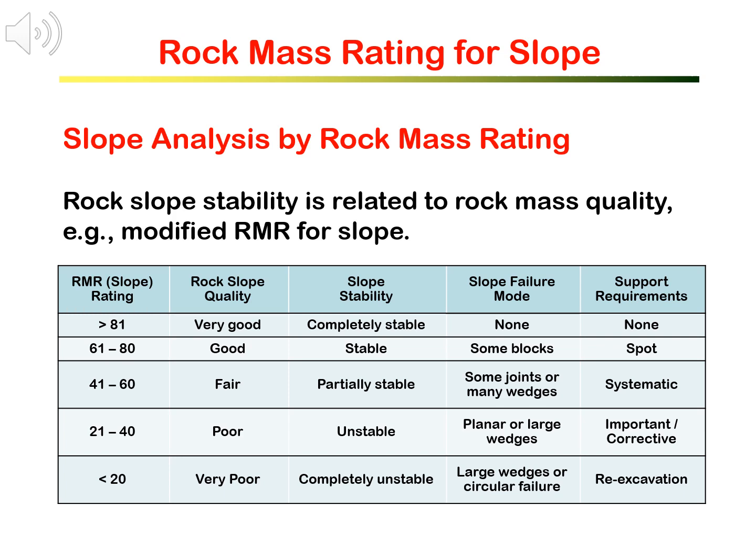It is a very useful practical tool for slope and stability analysis and the slope support design. Here is just a brief introduction to show that with RMR slope rating, column 1 and 2, slope stability or failure mode can be assessed in column 3 and 4, and support design are proposed in column 5.